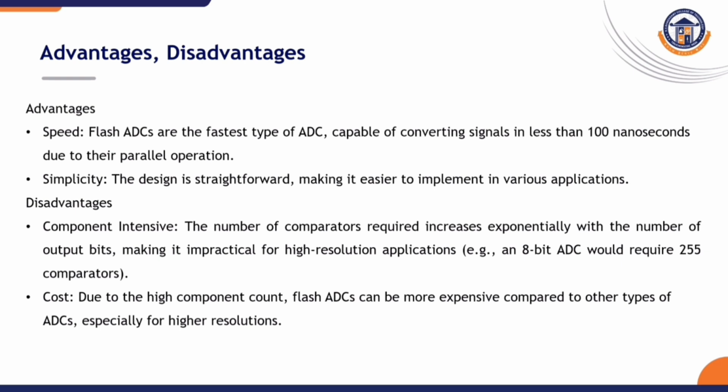If you consider the disadvantages, the main disadvantage is that it is component intensive. The number of comparators required increases exponentially when the number of bits increases. It is impractical for higher resolution applications. It requires a large number of comparators. Hardware complexity increases exponentially with resolution. Higher cost, not suitable for high resolution ADCs.